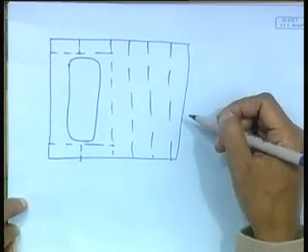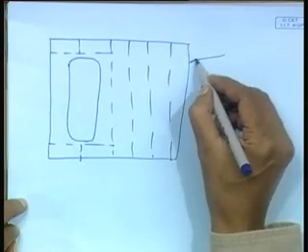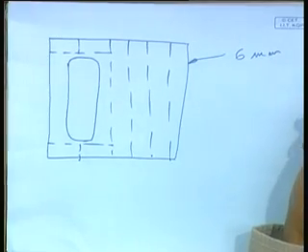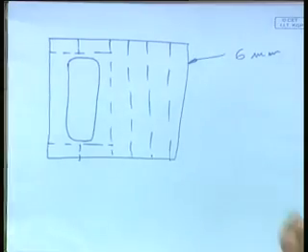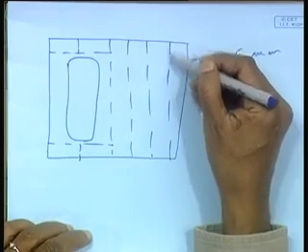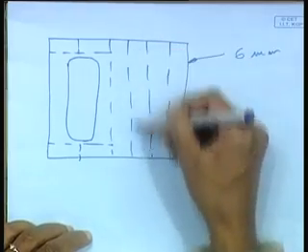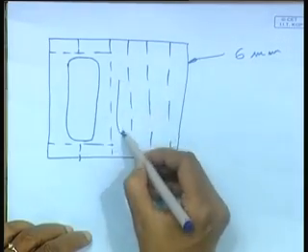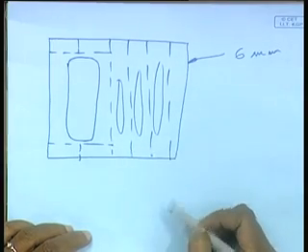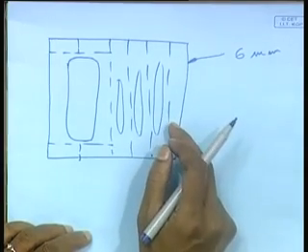These accommodation bulkheads are generally thinner plates, 6 millimeter plate, 5 millimeter plate. In the superstructure, much load is not there. In any case, they need to be stiffened. So, if you weld the stiffener, it will tend to buckle along this region, because they are thin plate.